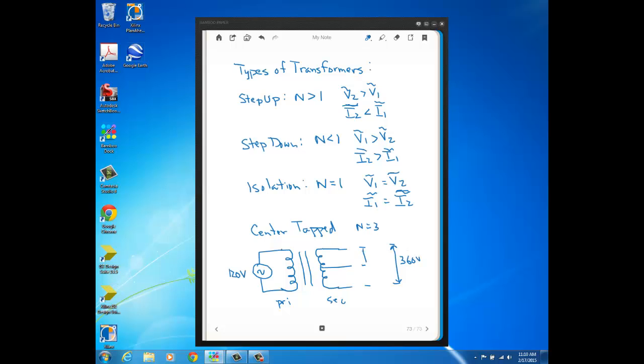But you see, between either outer contact and the center tap contact we get half the total of the secondary. So this would be 180 and this would be 180. So these center tap transformers provide a voltage division aspect to the transformer on the secondary side. There are also transformers that have multiple taps instead of just one center tap. You can get transformers where sometimes the secondary will have 6, 7, 8 or more wires coming out, where they've been strategically placed to divide up the voltage in a particular fashion for a particular design.